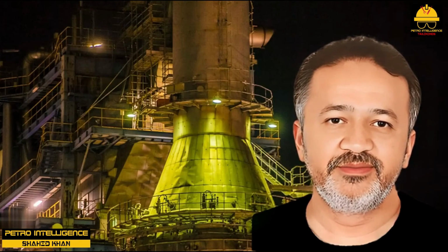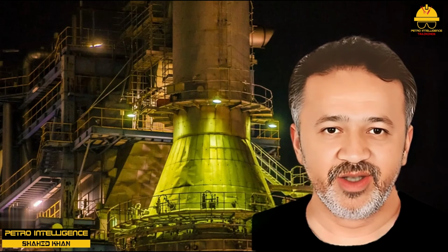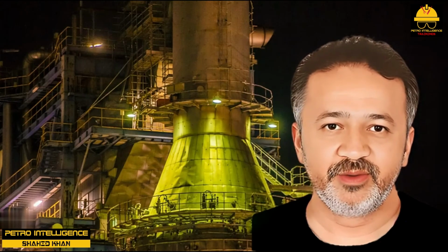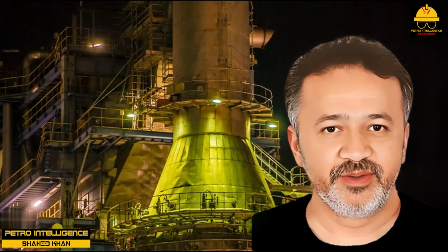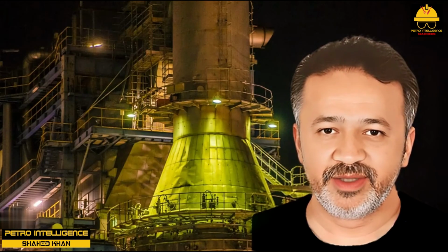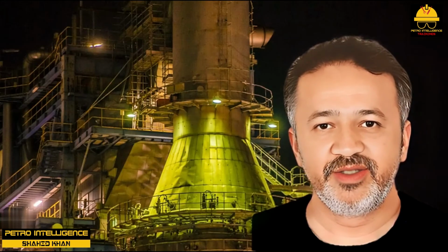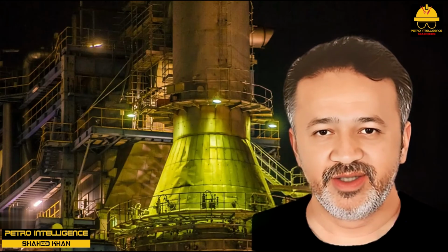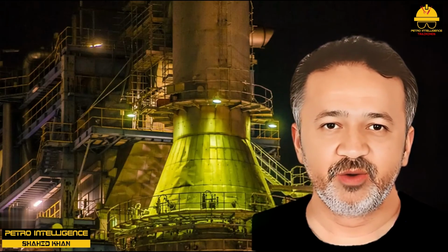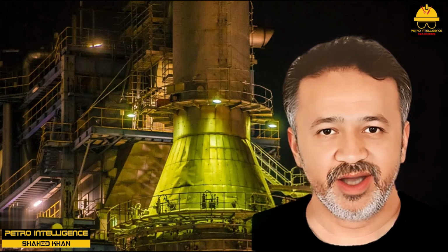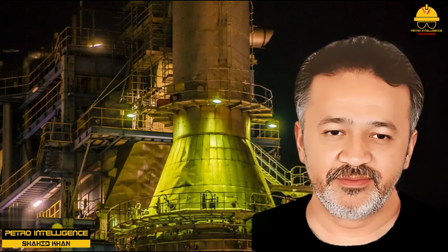Air preheaters. A typical air preheater will reduce the fuel required to liberate a given amount of heat by 10%. The debit for this improved thermal efficiency is a higher flame temperature and the possibility of overheating the radiant section. There is a clear advantage to fit an air preheater to a furnace when the firebox is running below a maximum firebox temperature. Three types of air preheaters are in common use.